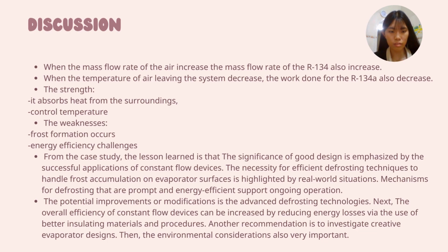For the case study, the lesson learned is that the significance of good design is emphasized by the successful applications of constant flow devices. The necessity for efficient defrosting techniques to handle frost accumulation on evaporator surfaces is highlighted by real-world situations. Mechanisms for defrosting that are prompt and energy efficient support ongoing operations. Hence, the potential improvement or modification is advanced defrosting techniques.